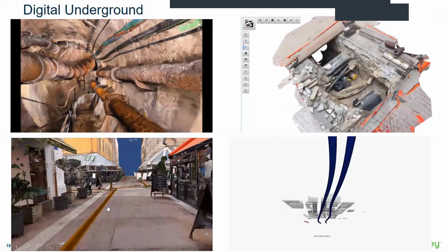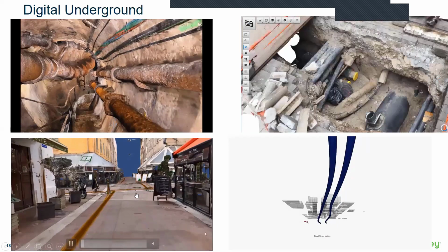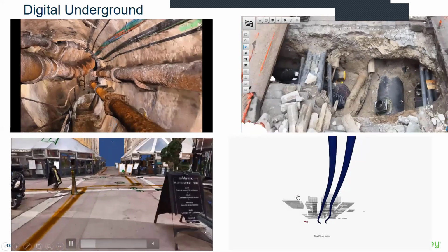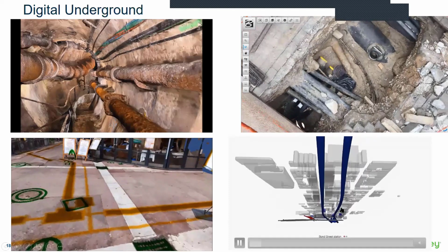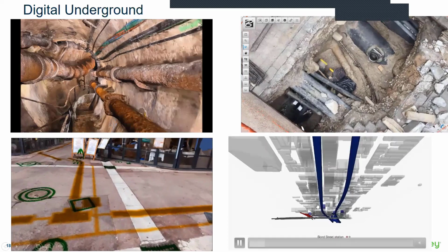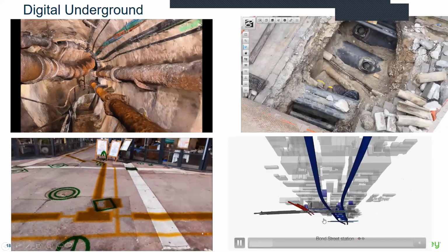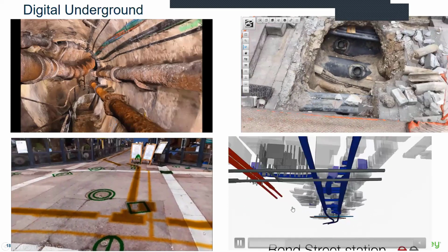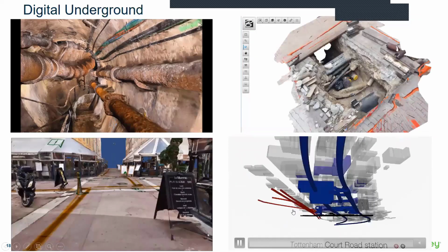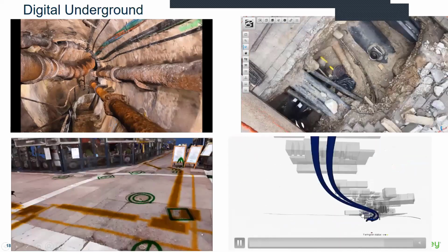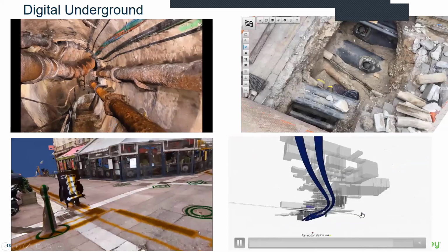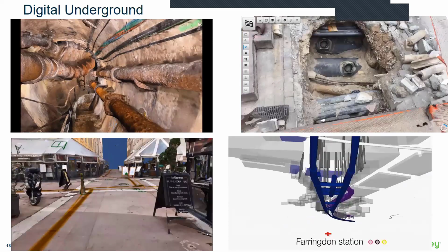And you don't have to start planning from above the ground anymore, because you will have a full underground perspective with a footprint of every building and different infrastructures with different layers of accuracy, because maybe those red ones are not validated, but the blue ones are already validated through ground penetrating radar or accurate as-built modeling.